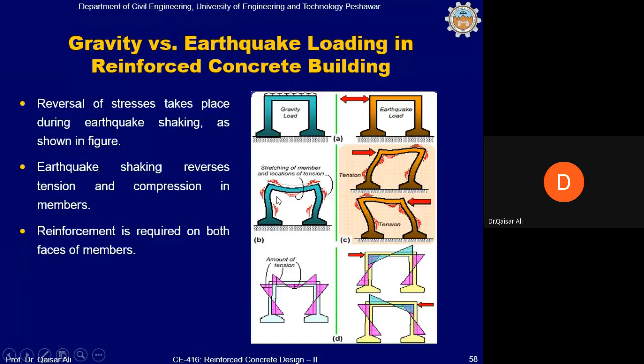So reinforcement must be provided in the beam at this location for this combined bending moment, which is produced partly by the gravity load and partly by the earthquake load. Understand? However, if you look at the midspan bending moment in the beam, at the midspan the bending moment is there from the gravity load, but there is no midspan bending moment coming from the lateral earthquake load.